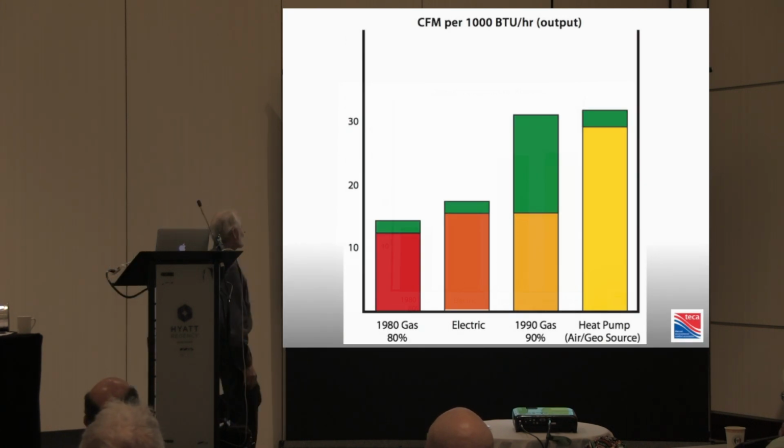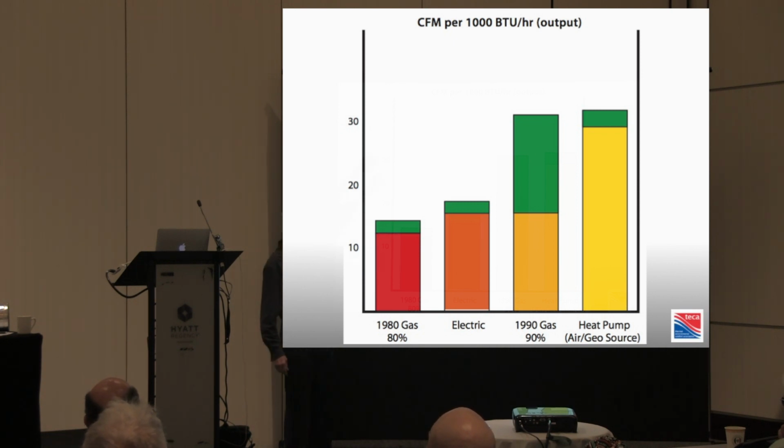Right now, if you have a gas furnace, it took approximately 12 cubic feet to carry 1,000 BTUs. Everything in our business is BTUs. 12 cubic feet packs a huge amount of punch because it's hot. But you take a look at a heat pump today, these things take 30 cubic feet per minute to carry the same degree of heat.